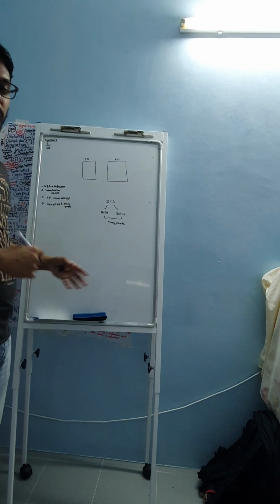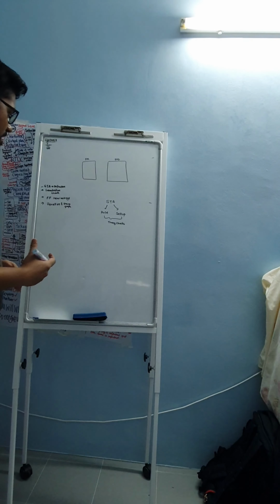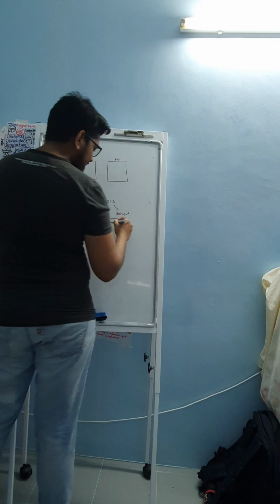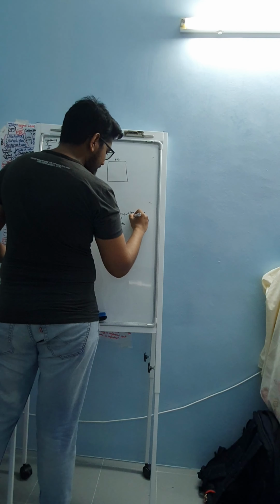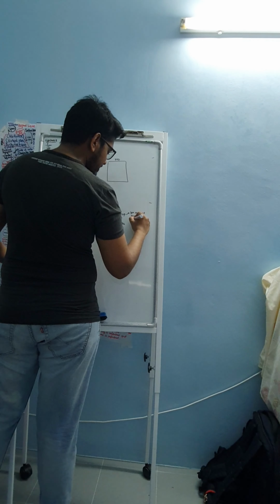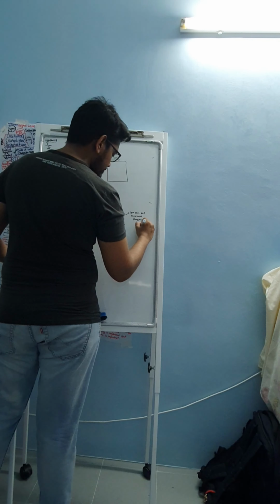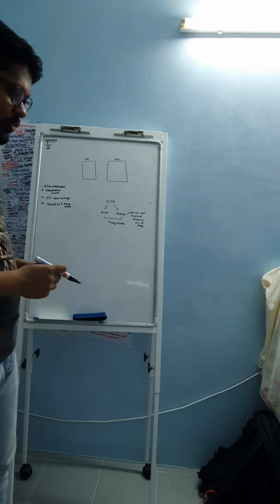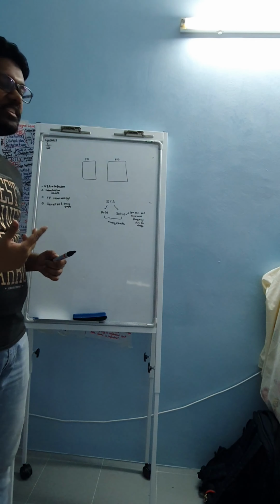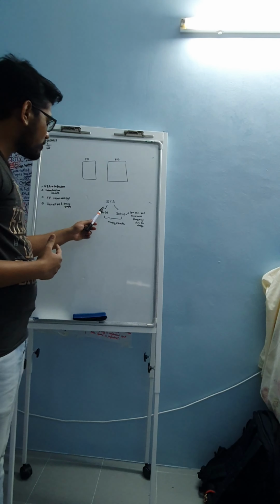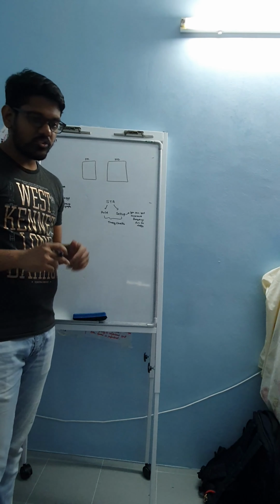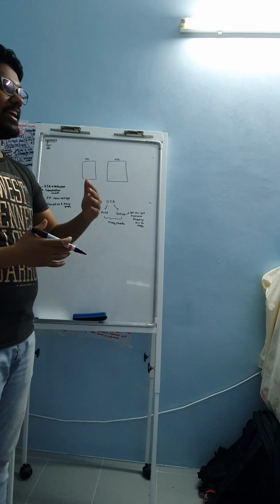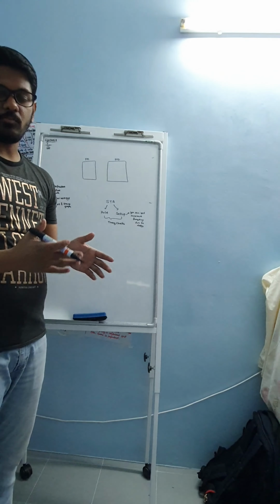And on top of that, for extra knowledge, normally from setup you can determine the maximum frequency of the design. People will be thinking, hey, how fast can my design actually run? That's the reason we talk about STA, the timing performance. It is derived from the setup checks, so from there you would know my design can work at this level.